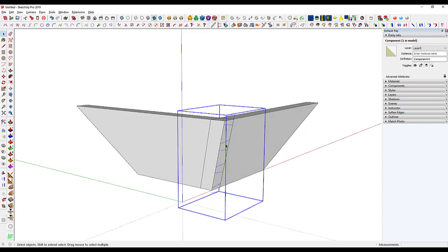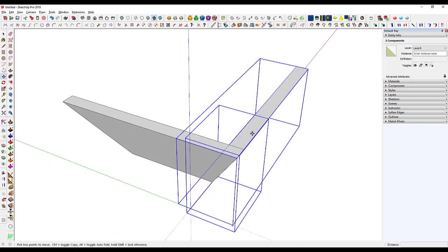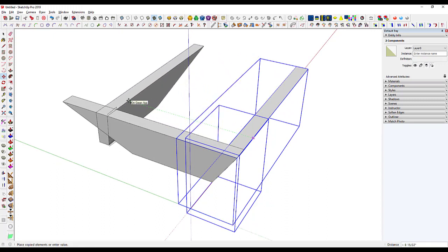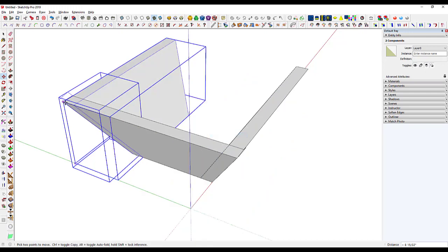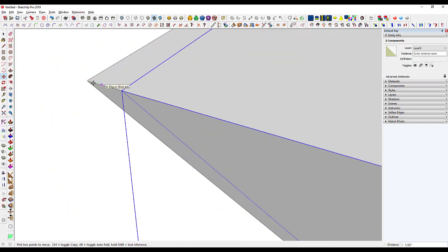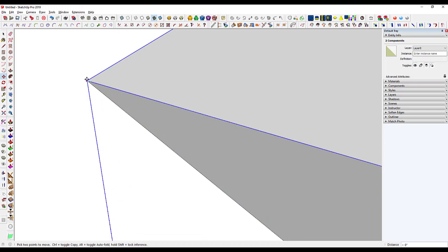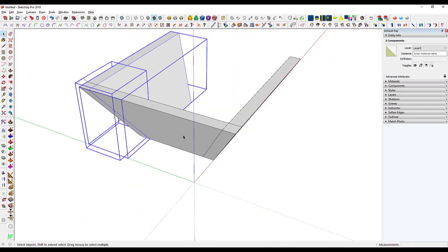I'll do that before I cut the dovetail sockets, but with that selected, I'm going to select the front side and use move copy this back in the green direction, and then I'm going to flip along the green direction. It's the same direction, I just moved it. Didn't quite move it in the right spot. Let's grab it there, put it at that corner, and then